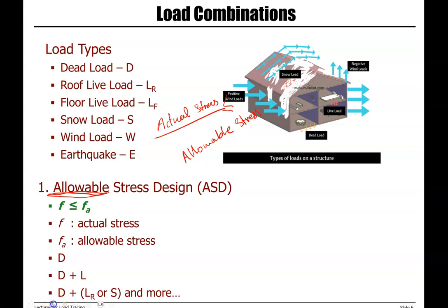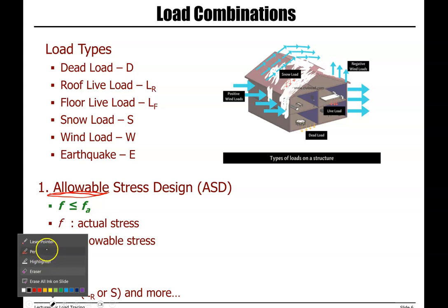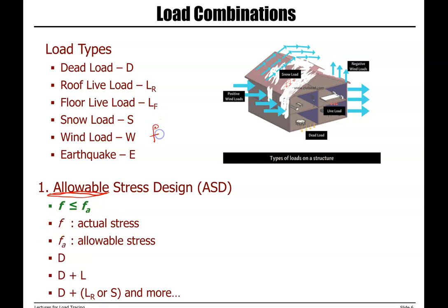So, one more time, the allowable stress design just says that the actual stress should be equal or less than the allowable stress. We will use the same concept to design foundation and to find cross-sectional area or width of our footing.